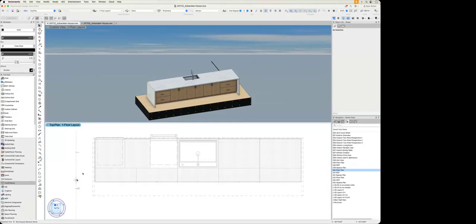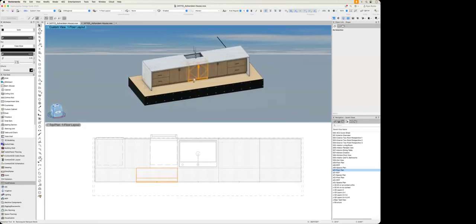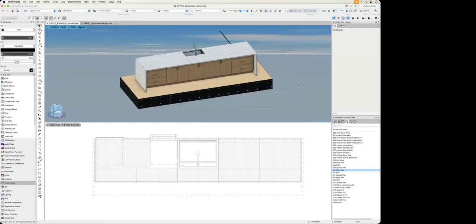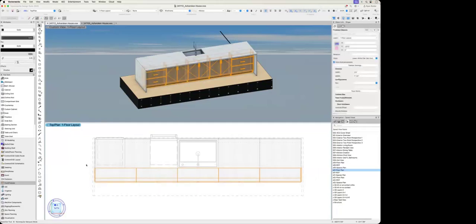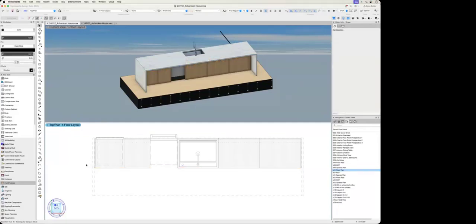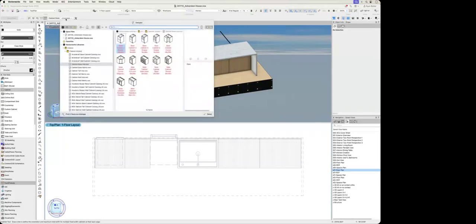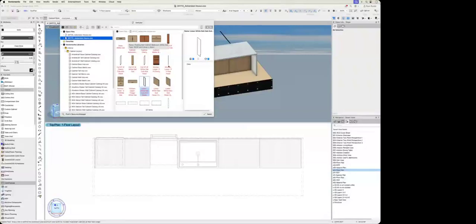Okay, so you can see here that we have a full kitchen island modeled already with the countertop and cabinets. So let's delete the first row here, this front row of cabinets, and rebuild them. The cabinet tool is located in the furniture and fixtures toolset. So if I have that toolset selected, I can go to cabinet, and here I could choose from placing an unstyled cabinet or a styled cabinet. I have a bunch of styles, and also there's some that are in the resource manager. So let's take a look at some of them.